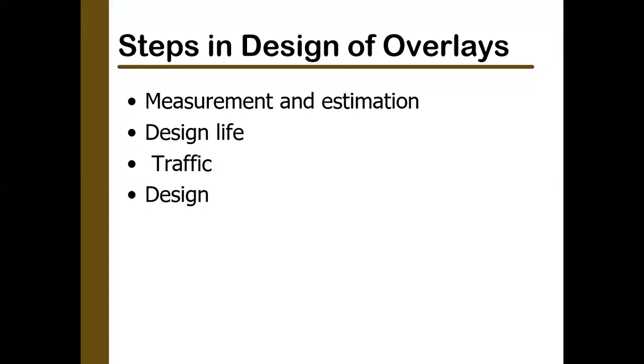When I mean the measurement and estimation, I mean the structural or non-structural evaluation of the pavement. What we do normally is to find out the condition of the pavement non-structurally. What I mean is just doing the pavement condition index survey.